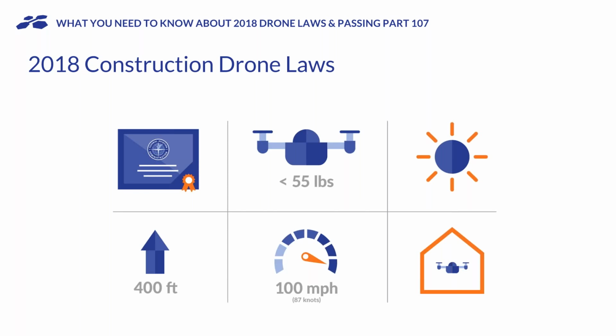The surveying drone or the mapping drone, whatever you're using, it has to weigh less than 55 pounds. So somewhere under that range. Again, most of the commercial options out there do, unless you're doing something like transportation. You have to fly in daylight or twilight. Maximum altitude is 400 feet above the ground. Maximum speed is 100 miles per hour or 87 knots.